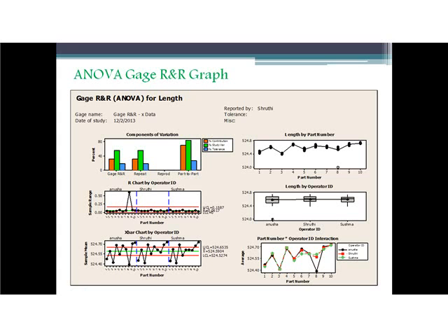Coming to the X bar chart, it is the one which compares the part-to-part variation to the repeatability component. In this case, many points are above or below the control limits. These results indicate that the part-to-part variation is much greater than the measurement system (measurement device) variation.